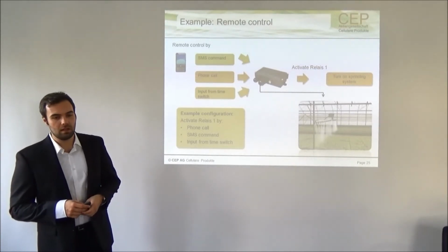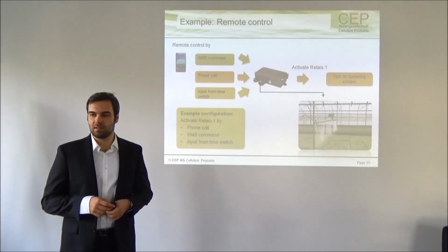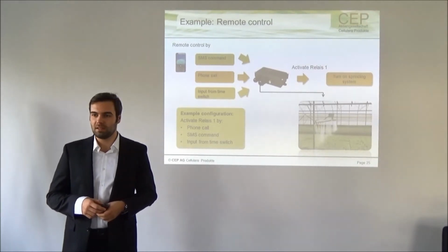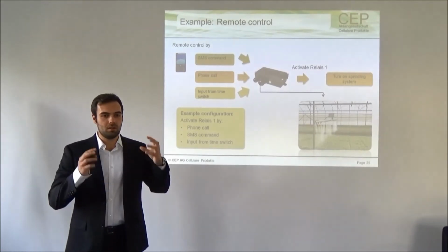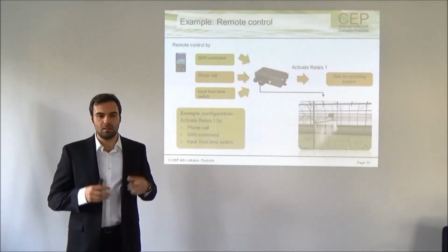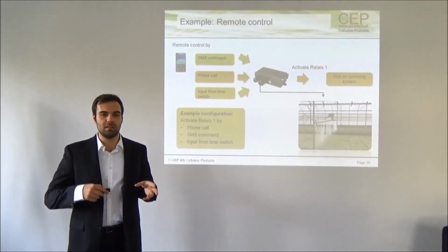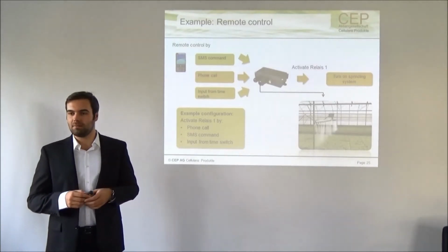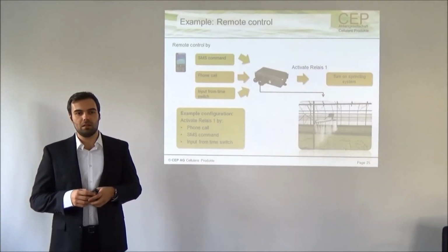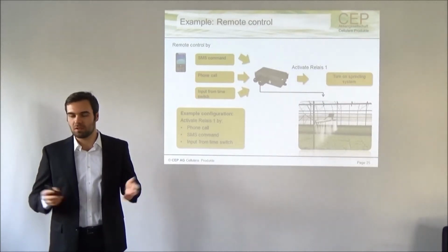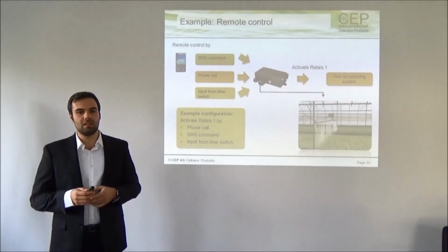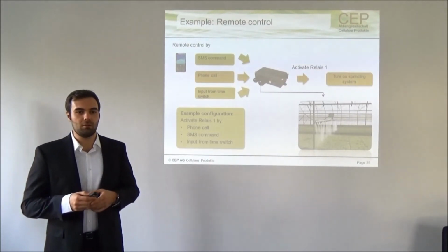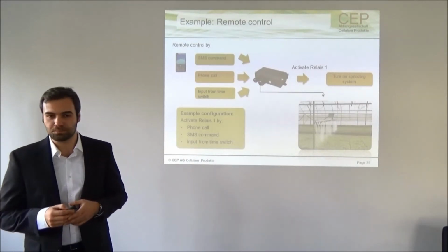For remote control, we have a few customers in Germany that use this device for controlling a sprinkling system. So you have the chance to build in the STD inside of the sprinkling system, and you can send an SMS to start the system or call the device, and also you can have some external input from a time switch, for example. So in a specific time frame the STD will automatically react and start the sprinkling system.